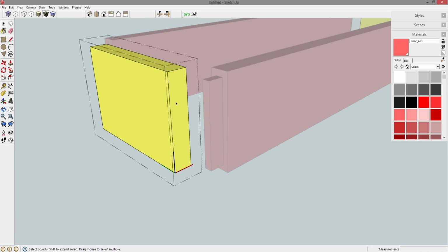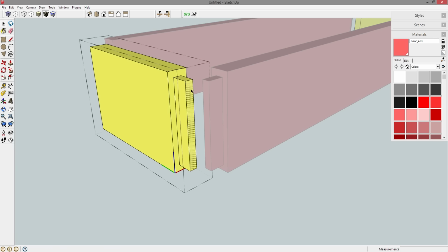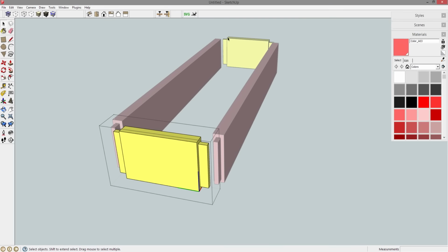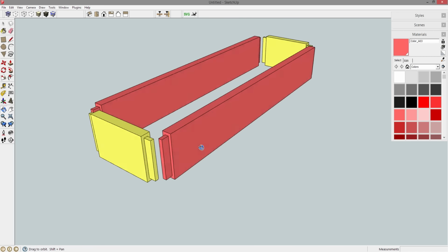Same exact process, double click to edit the part, F for offset, come in 3/8 of an inch. Spacebar, click the middle to select it, P for push pull, and let's pull this tenon out 1 inch, enter. Spacebar, click that face again, M for move, and let's press Control to bring up copy, constraining to the green axis, and drop it off on this back edge over there, P for push pull, and let's push it that direction 1 inch, enter. Exact same process, and now what is a copy, which is back here, is updated as well.